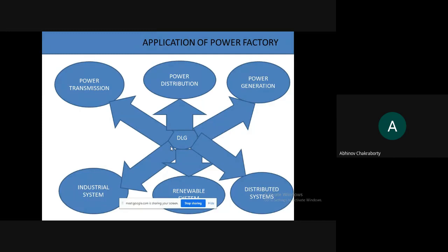the power capacities of your generating unit. Generally, we go with the synchronous type of a generator, and you can specify the ratings over there. Once you have specified the ratings, then we move into the transmission part. So before moving into the transmission part, you will be needing your buses, and after your buses, you will be needing transformers. In between the buses, obviously, you will be needing some isolators, you'll be needing some protection units. So all these are readily available, and you just need to mention the ratings. Right, but yes, the ratings have to be correct. Until the ratings are correct, your simulation ought to go wrong.